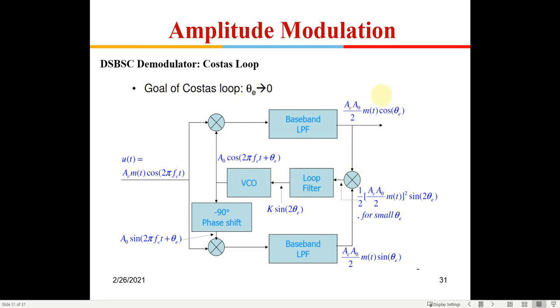So you will find that the control voltage is proportional to theta. So you have a feedback loop right here. If there is an error, a voltage which is proportional to the error will be given to the VCO. It will correct the VCO. So this VCO will slowly slave to the correct frequency, right? Whenever there is no error available here, there will be no correction voltage given here. So the VCO will oscillate at the desired FC value, right?